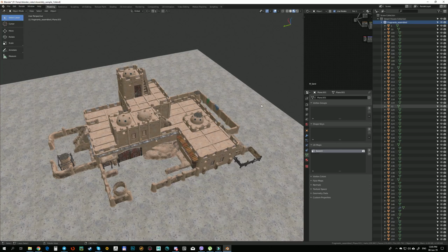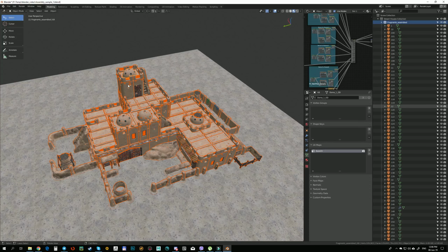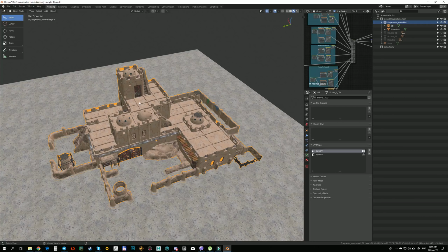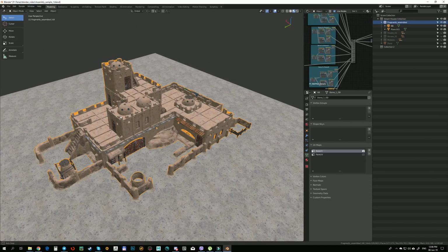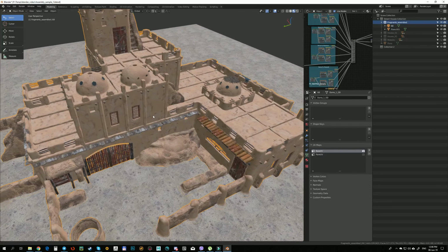Select lasso, then I change it back to select, Control Shift click on the plane because I don't need it, then I need to Shift click on this element to make the outline brighter, and hit Ctrl J to join everything together. So all my meshes are combined together.